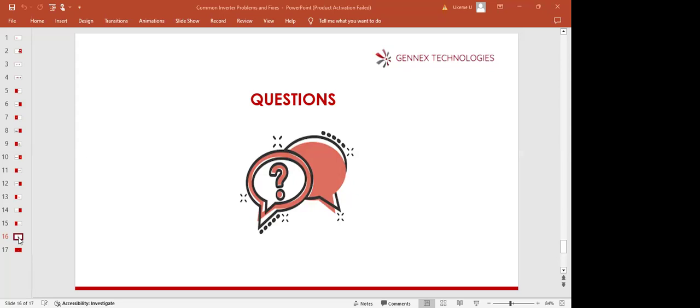Thank you, Engineer Kunle, for that wonderful and impactful session. Now, I got to know, and others too, that when you have error 07 on your inverter, you shouldn't retrieve it and bring it to the office. Imagine a lot of persons that have done that. Consider the cost of sending the inverter and the kind of things that the client will have in mind towards you. They will think maybe you are not professional enough. So once you see error 07, you will know that this one is overload.